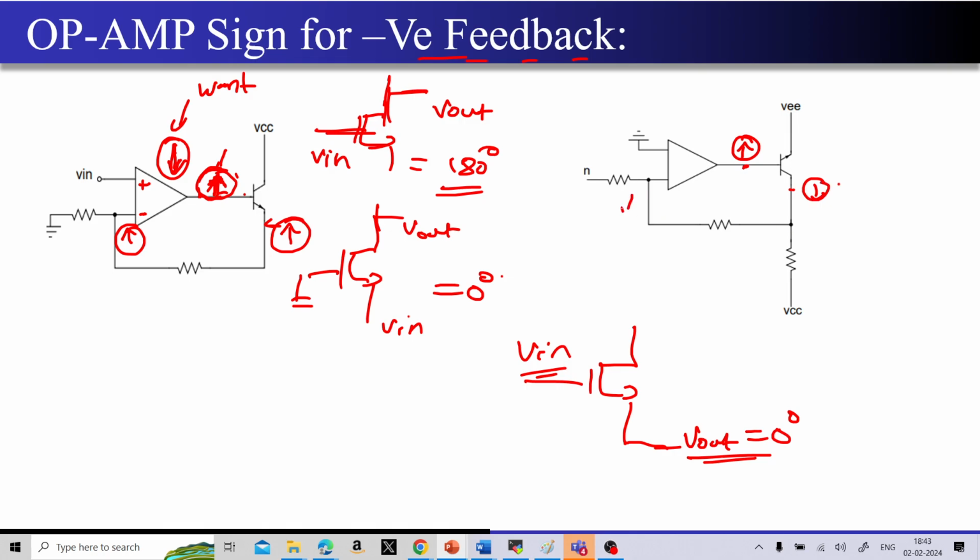And what I want is, even this particular value over here has to go down, because I want to cancel out the disturbance. So if this voltage is going down, even I want this voltage to go down, so there has to be a positive sign, right? Because if I put a negative sign over here, then this value is going to go up and the system will turn out to be positive feedback, right? So I hope that particular point is clear. So this has to be plus and this has to be minus in this particular case.